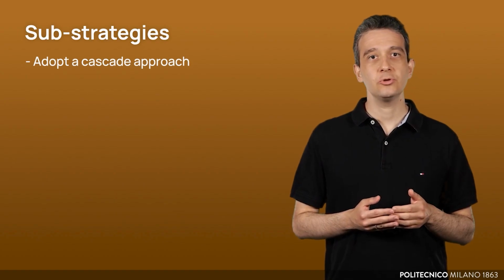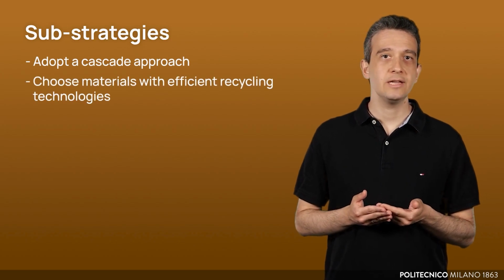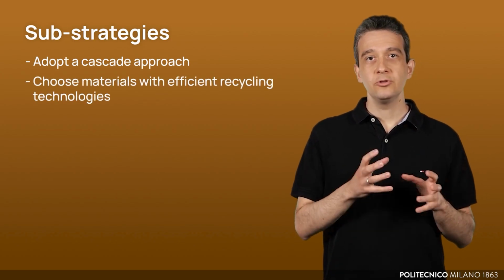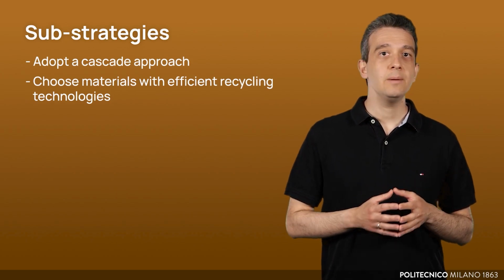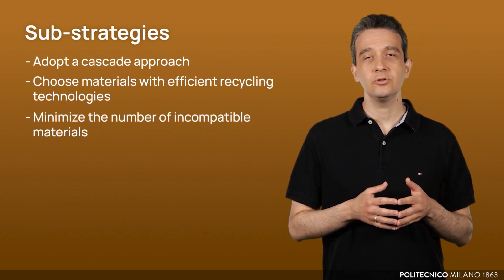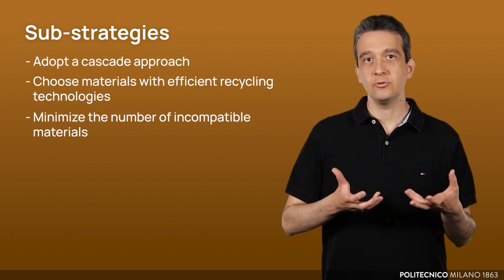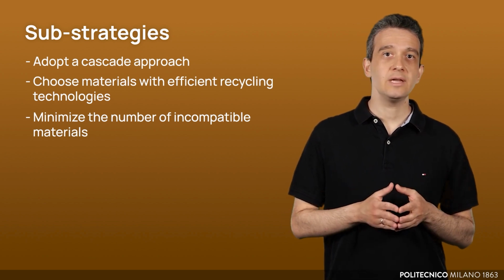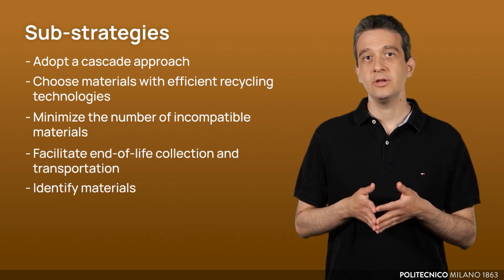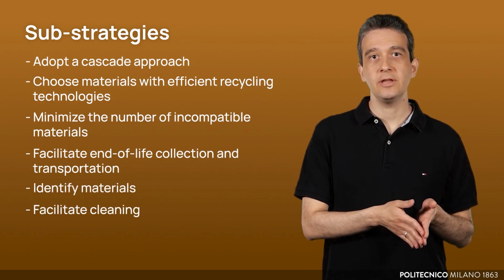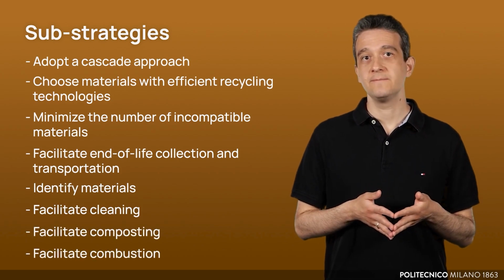Other sub-strategies to extend the life of materials include choosing materials with efficient recycling technologies, meaning those that best retain their performance characteristics after the recycling process, minimizing the number of incompatible materials, that is, materials that cannot be recycled together, such as plastics with different melting points. And finally, facilitating collection and transport after use, identifying materials, making it easier to clean the material, and facilitating composting or combustion for energy recovery.